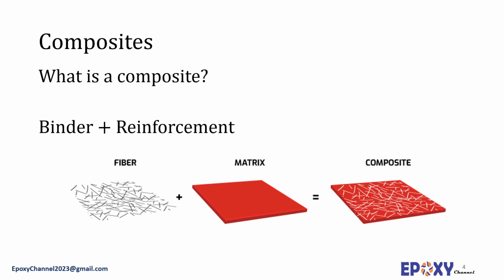The reinforcing fiber can be either continuous or discontinuous in length, with strength and stiffness much greater than the matrix. The resin matrix can be either thermosetting or thermoplastic. Polyester and epoxy composites are the most common matrices in thermoset composites.